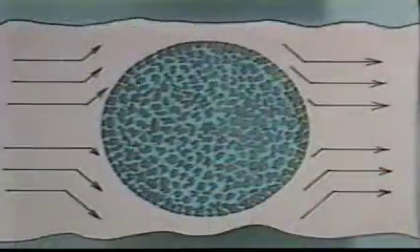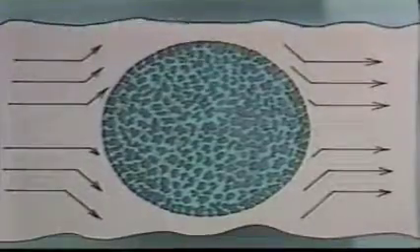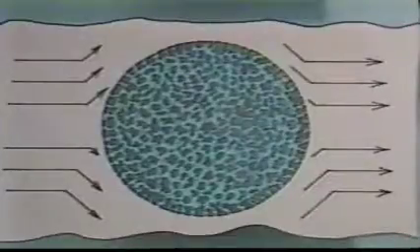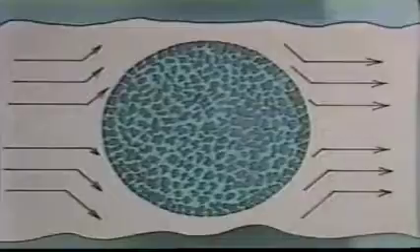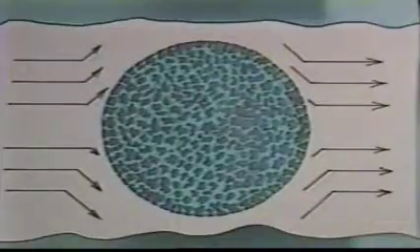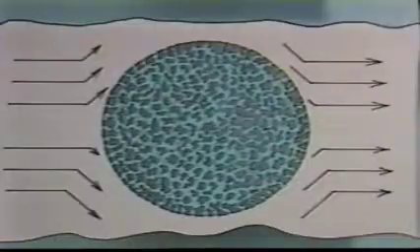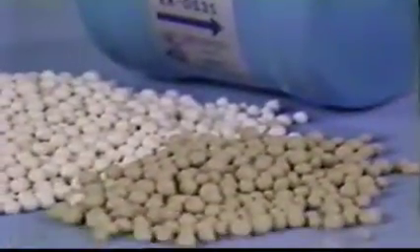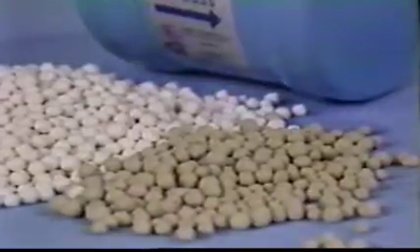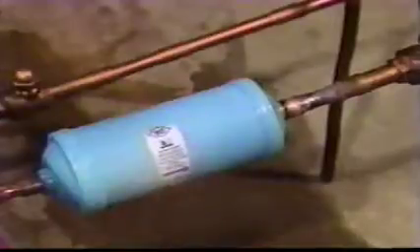It is important to note that refrigerant flow occurs around the desiccant material, not through it. This special characteristic of an adsorbing material will ensure that pressure drop stays as low as possible, as long as possible. The desiccant material can either be in block form or beads, depending on the application. We now start to see the important differences in filter dryer performance.